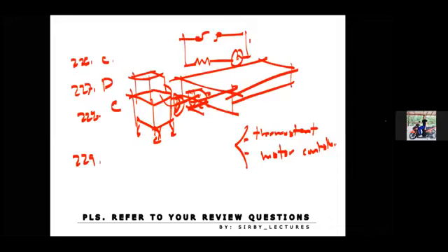Okay, so again, let us read number 229. Which of the following is not correct? Take note, it's the one that is not correct if the fuse element in an entire series circuit melts due to excessive current. For letter B, the fuse element is opened, so this is true. Letter C, the fuse protected the circuit components against overload. Yes, this is true. Letter D, the fuse is replaceable. Yes, you can replace that. So the answer here is letter A.